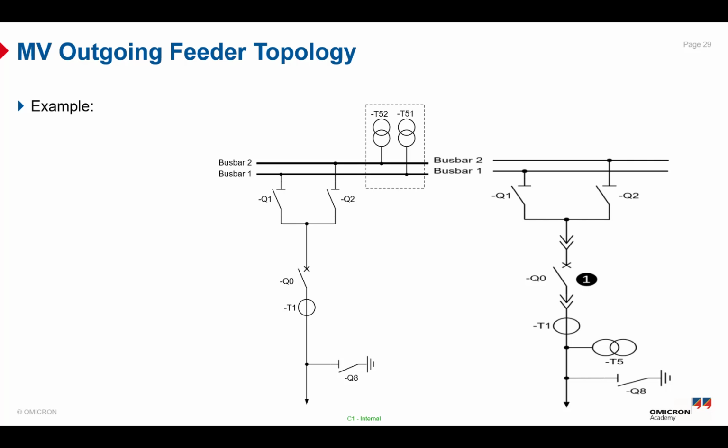And also, to explain the difference between the circuit breaker and the disconnector: the circuit breaker with the arc quenching medium can be used to interrupt the fault current and to clear electrical faults. The arc quenching medium in the circuit breaker, like air, SF6, vacuum, or oil, is used to extinguish the arc when interrupting current. So the circuit breaker can operate under both normal and fault load conditions. On the other side, the disconnector or isolator provides a visible open point for maintenance and safety, so there is no arc quenching medium.